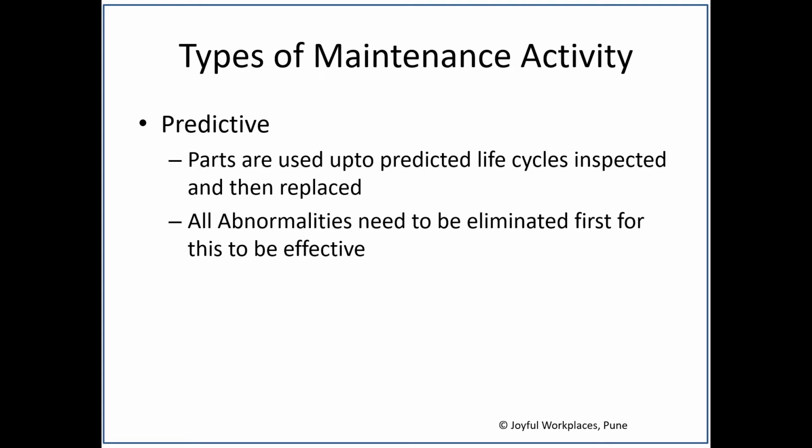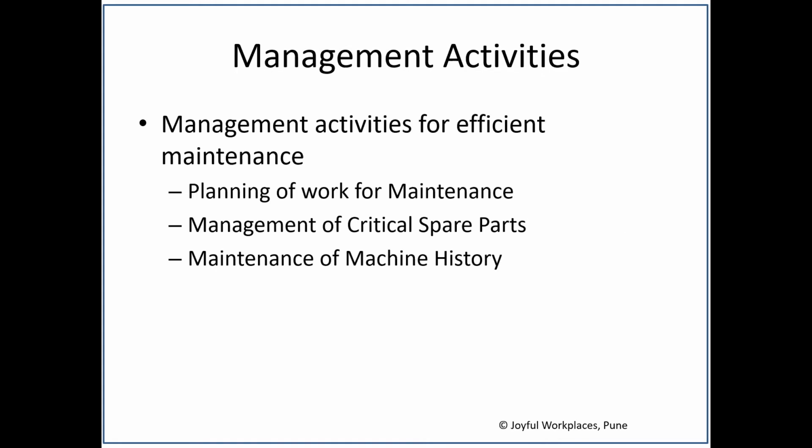What do you mean by all abnormalities need to be eliminated first? So one cannot directly start with predictive maintenance. One has to ensure that preventive maintenance and operator maintenance are basically in place. Then only will predictive maintenance be more effective.